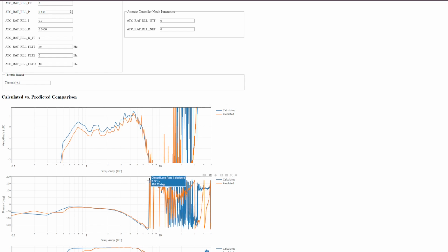So we're looking around 7.23, 7.32 hertz. Yeah, perhaps a little bit lower on the D term, drop that down a little bit. So you can see we're dropping past the 3 dB, and this is just scraped past the 1 dB, a bit of noise, hard to see exactly where it is. And so that's going to be my P and D terms.